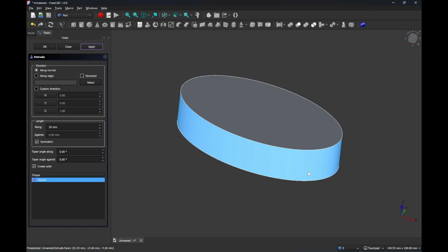But when we're using the part workbench, we can have multiple, separate objects, where you can't do that in the part design. You have to build a body singularly, fully, no 2 parts can exist in the same model. So click OK.